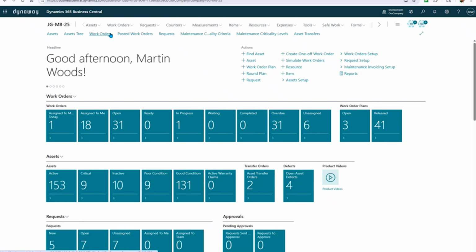We also do things that are called measurements. So measurement would be something tied to an IoT device. An IoT device is going to look at things like frequency, voltage, pressure, could be time as well, temperature, all this stuff that we're going to monitor in real time. So you're going to say when the pressure gets above this level or below this level, or the temperature is this hot, above this level, then fire off this work order. So pressure's too high, temperature's too high, fire off the work order.